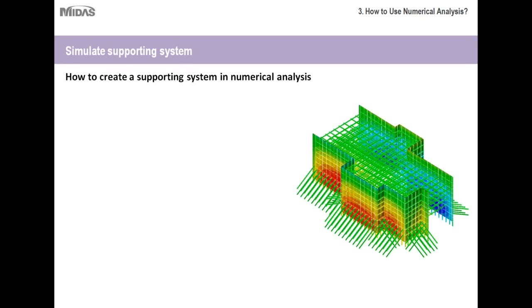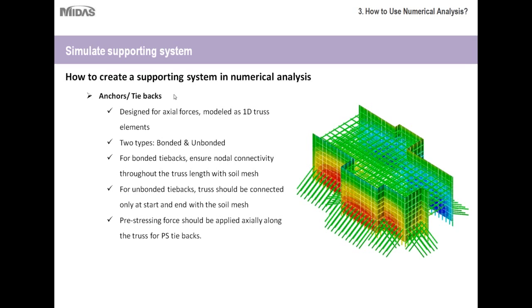Okay, so now let's discuss how to create a supporting system in numerical analysis. So here we have different sorts of supporting systems, anchors and tiebacks. Just to explain this picture here, here are your bracings, your sheet pile walls, and then these lines here, these 1D elements, are your anchors, and then these lines here are your bracings.